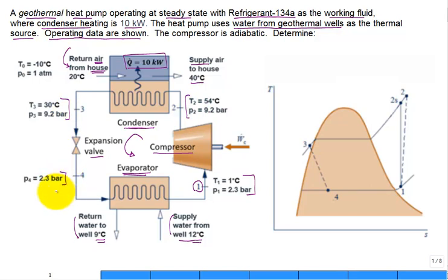They also give us a temperature entropy diagram, a T-s diagram, and we see that state 1 is shown to be slightly superheated, and then at state 2 and 2s, so that we have some isentropic efficiency for this compressor, or there are some irreversibilities in the compressor.